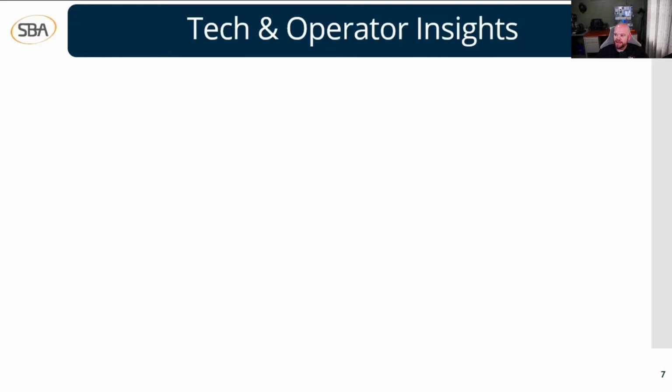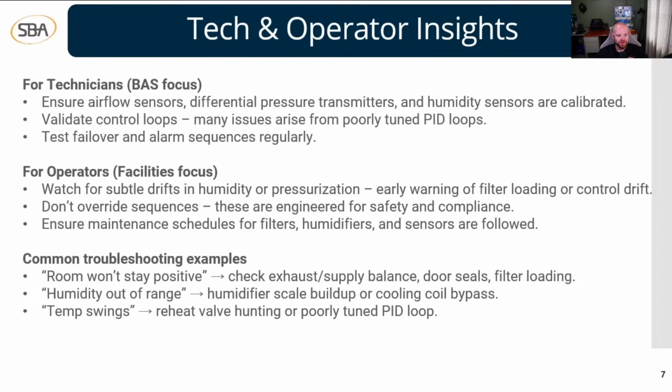Next here, we're going to look at some technician and operator insights. So for technicians, this is a BAS focus up here at the top. The first thing here is to ensure airflow sensors, differential pressure transmitters, and humidity sensors are all calibrated.